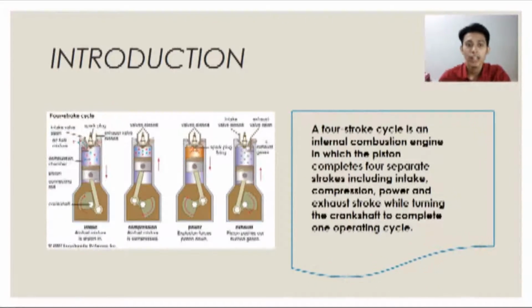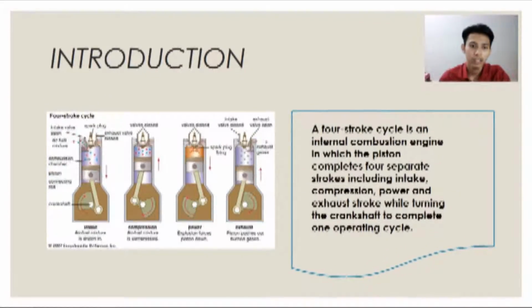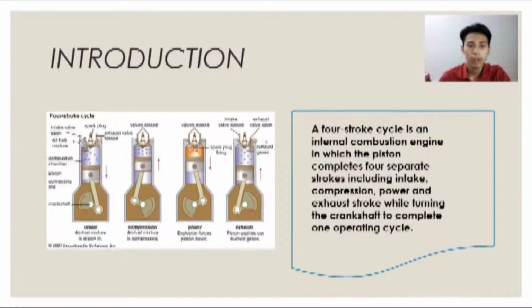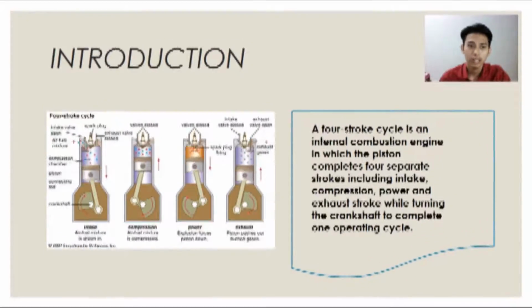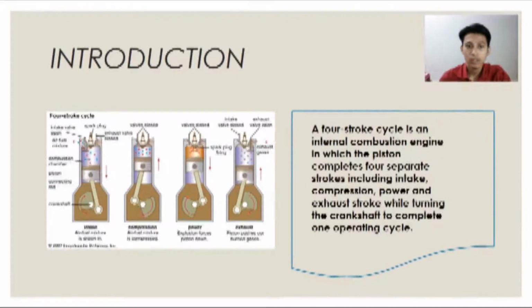And the last one is the exhaust stroke, where the intake valve is closed and the exhaust valve is open, allowing the piston to push the spent exhaust gas out of the engine when it rises. And then the fourth stroke, which completes one cycle, is done and the process will be repeated again.